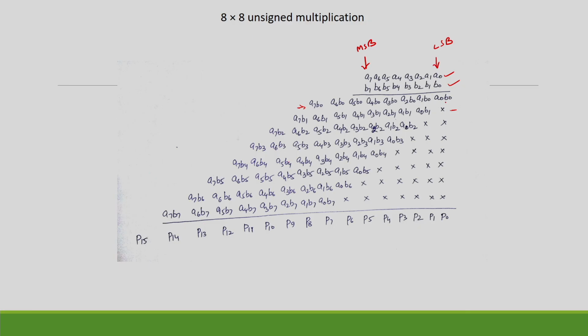So, here to get the final 16 bit output, we are performing 2 8-bit by 8-bit multiplications. The result can be, maximum result can be 16-bit. Okay. So, that 16-bit result will be shown by P15 to P0, this is LSB, this is MSB. Then how to implement this P0 to P15? So, P0 implementation is basically AND gate. Okay. Nothing is to be added, AND gate.